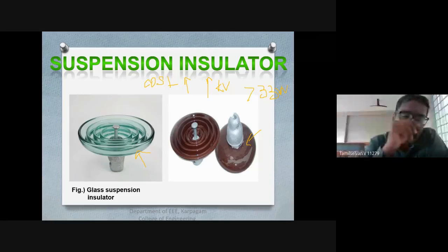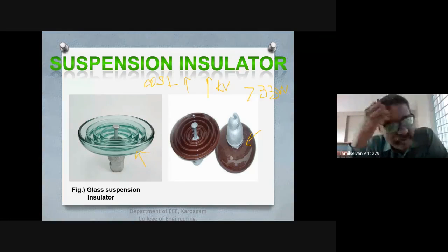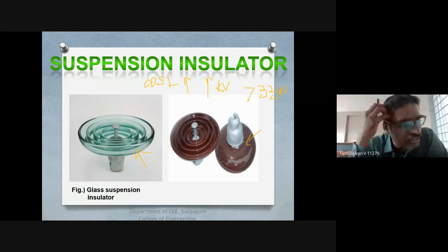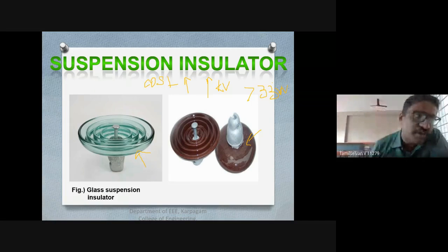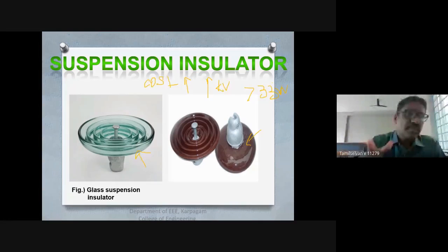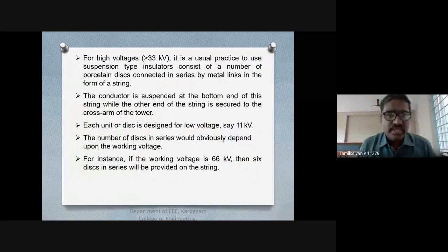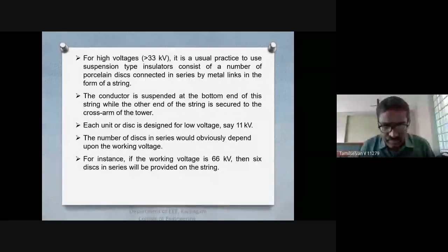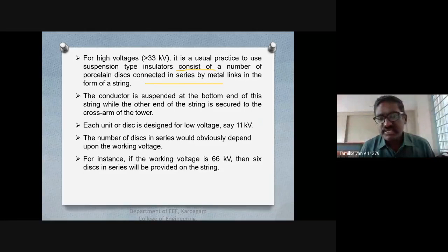So to have lesser cost with high mechanical strength and dielectric strength, we go for suspension type insulators. The number of porcelain discs depends upon the voltage. A number of porcelain discs are connected in series through metallic links, and that forms your strings.